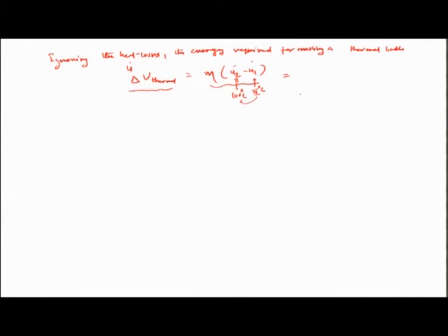And so, if we consider the mass that we calculated in the earlier equation through the specific volume term, that is 6.867 times 10 to the power of minus 15 kg, times U2 at 100 degrees Celsius, which has been given in the question as 2506.5 kilojoule per kg, and U1 at 20 degrees Celsius, given as 104.88 kilojoule per kg.